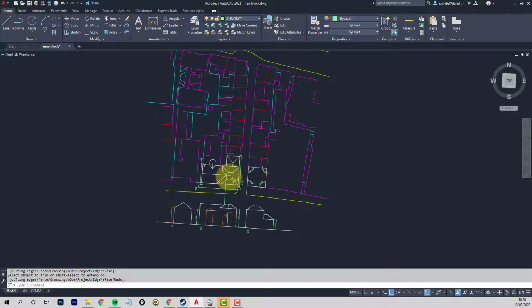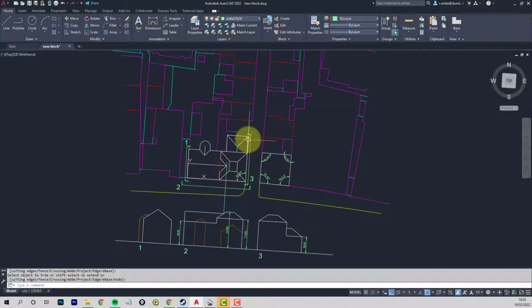Now you could rotate everything so that it's a bit easier to model in SketchUp. We could put this back to being horizontal, but you're then not at the true orientation, and if you're not very careful with the base point for the rotation, then if you want to bring other bits to the model, the chances are they're going to end up in the wrong place. So I'm going to keep this all at the true rotation.